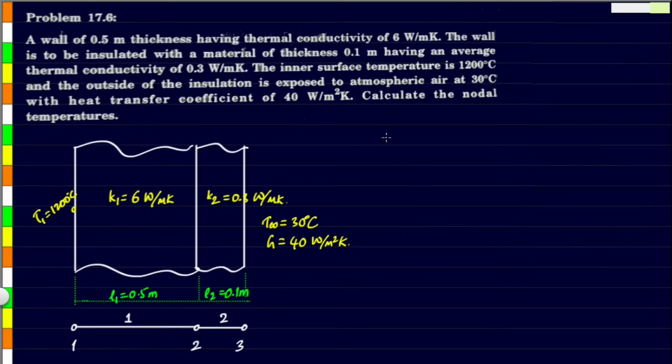So first let us start with the relation. Fine. So we need to find a relation between thermal forces or the heat flow equation, and that heat flow equation will be equal to the global thermal stiffness matrix multiplied by the temperature matrix. So this is the equation we'll be using in order to find all the temperatures. We should be able to expand all these and write them down. So let's first expand the thermal forces.